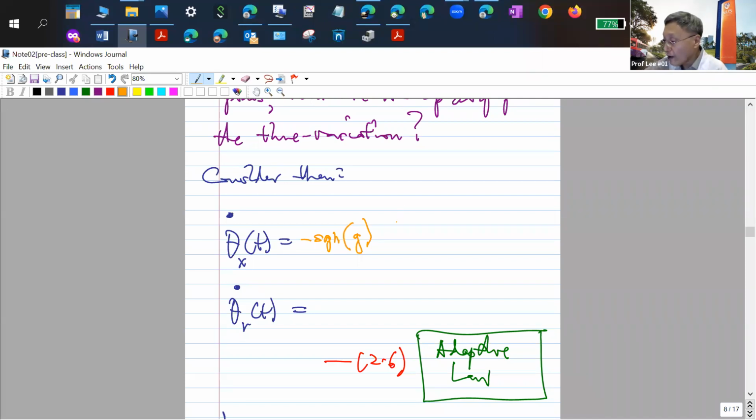Then, instead of the small scalar number, because now we are working with a whole set of state variables, not just YP, instead of just the scalar gain gamma 1, this now generalizes to the capital gamma matrix. And gamma 1, remember, was required to be positive. Here, what is required of the gamma matrix is that it should be symmetric positive definite. So go and check out your undergraduate mathematics for what a symmetric positive definite matrix is. So it should be capital gamma.